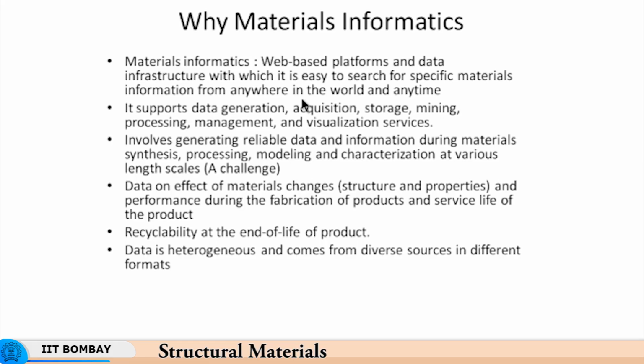Generated data will be inaccurate because you have assumptions which stand between you and reality. The acquired data using sensors would have limitations of the sensors, drift in the sensors due to temperature or whatever, the sensor getting loaded and things like that, as well as noise. So, interference of different signals, noise, etc. will be another issue when you acquire data.